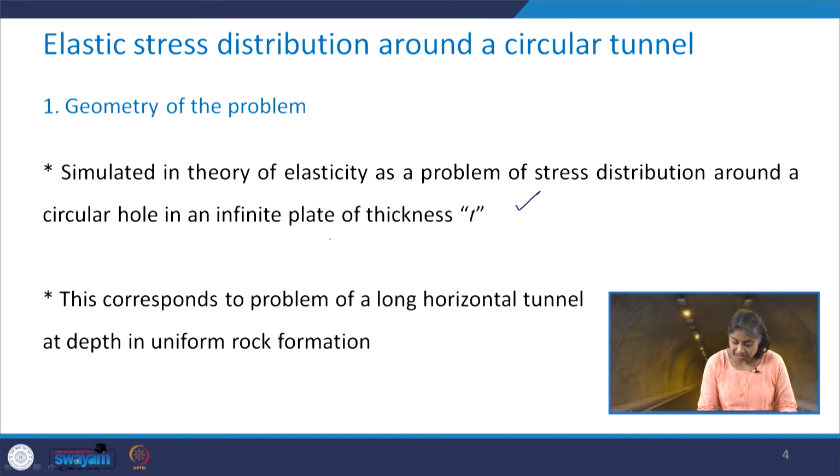This problem corresponds to a long horizontal tunnel at depth in a uniform rock formation. Please understand that rock formation can never be uniform, but as a starting point, these are the assumptions which we are considering while going for the elastic analysis of the circular tunnel.